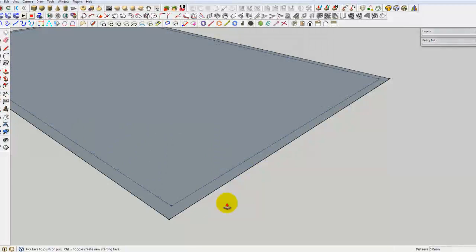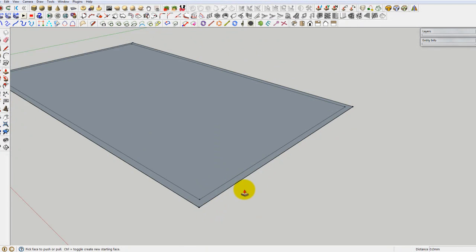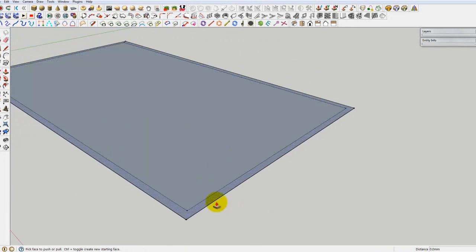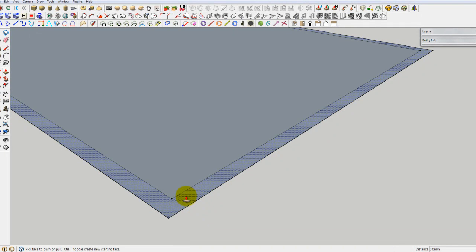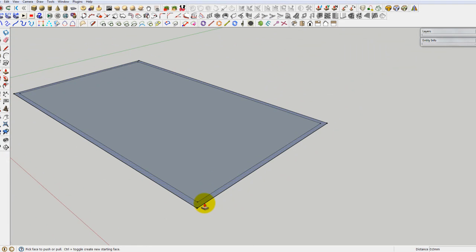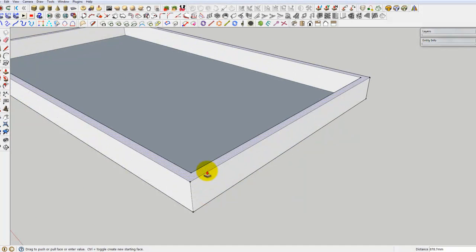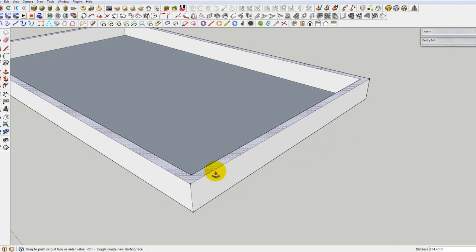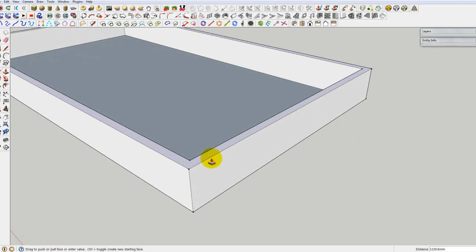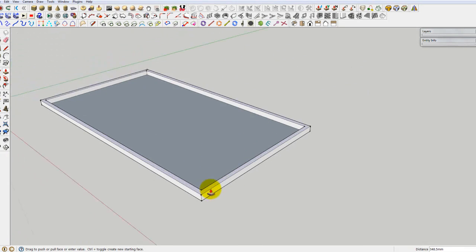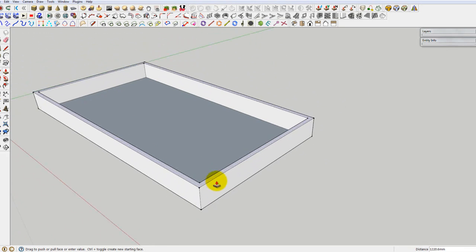You just hover over some plane and it gets highlighted, right? This is basically showing you that you can extrude it. It's something similar to extruding surfaces in other software. So you can extrude these surfaces by just clicking anywhere on this one, and what we see here is that we're just extruding it normally, right?